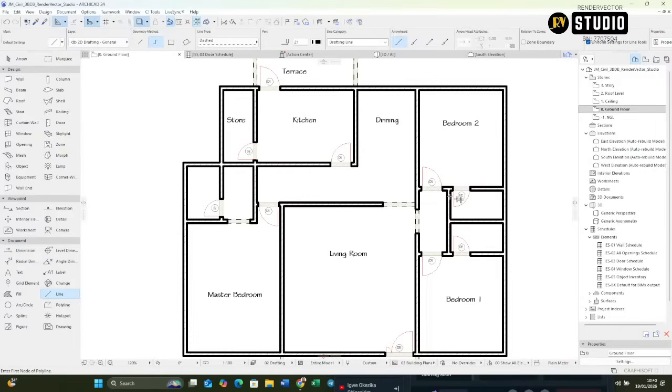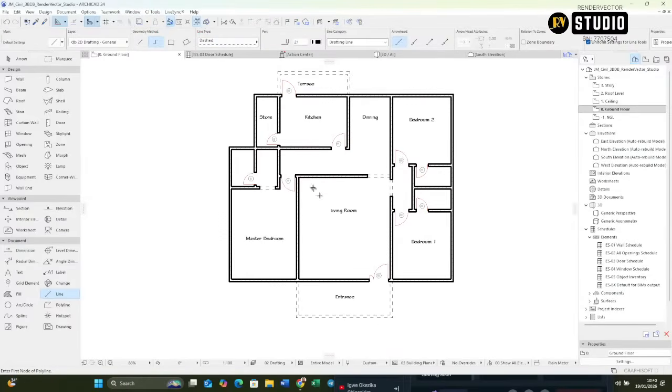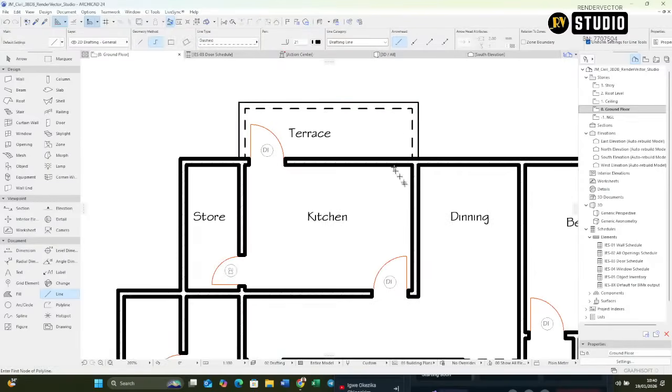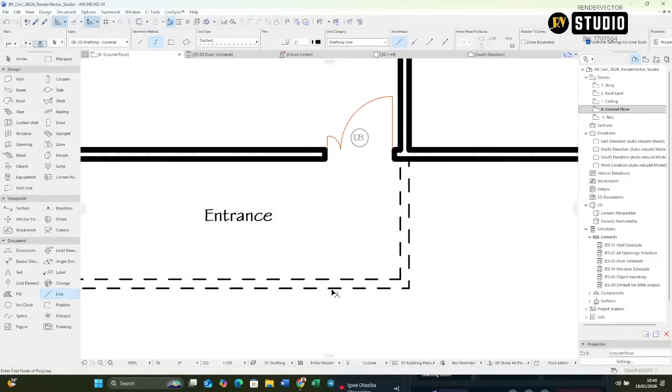So if we remove the trace, you'll see the floor plan is coming out well. And normally, the outside part here is meant to be solid line. Then the inside, so as to tell you that something is there cantilevered. This one also is solid line.